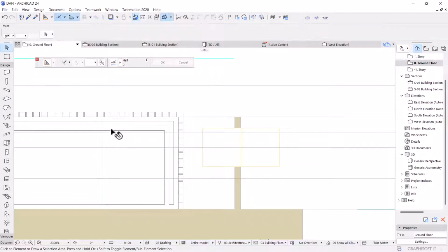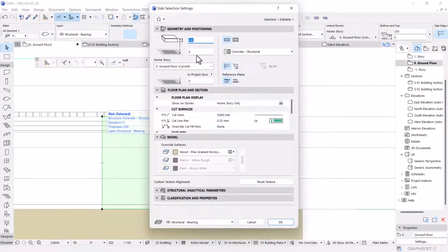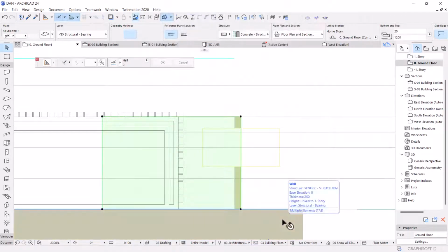Okay, so you want to change the location of this slab to place it somewhere where you will see it properly. So let me do 1200. And the thickness, again, we want it to be 20, like our wall thickness. Also, this is one way if you want to draw your own cabinets, kitchen cabinets, or in the bedroom when you're drawing the closet or wardrobe, you can use this trick. You can draw using the slab as well as the wall tool.